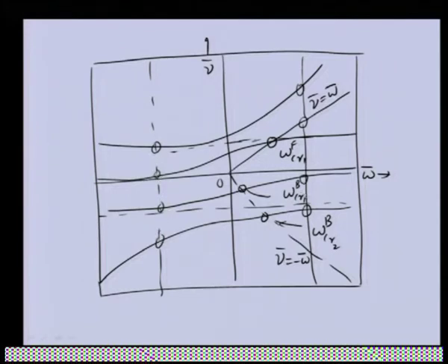frequency. And this particular diagram is called the Campbell diagram. And this is a very famous diagram for obtaining the critical speed of a rotor system, in which we plot the whirl frequency with the spin speed. What is the whirl frequency variation with respect to the spin speed?